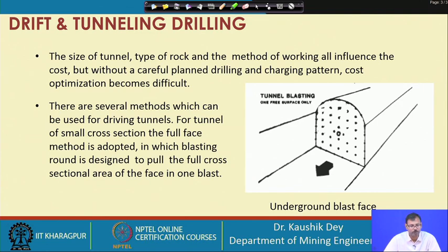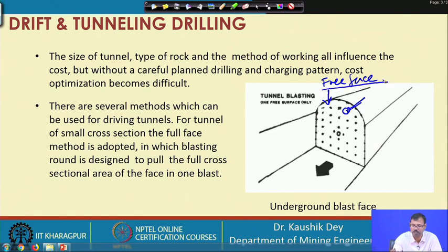For that we have to carry out the drilling operations in the mine, the drift or the tunnels. These are the drill holes that have to be drilled inside the rock mass, where this is the only available free face. This one free surface creates the confinement of the charge placed inside the drill hole. The confinement is very high.